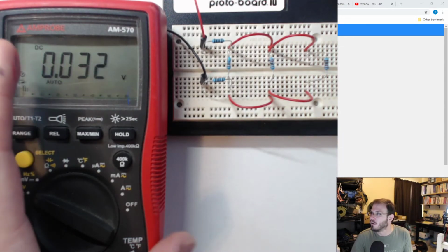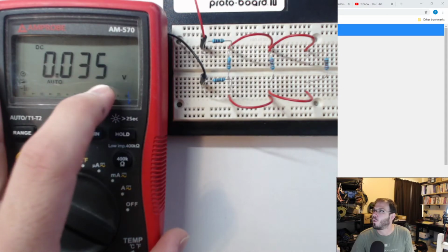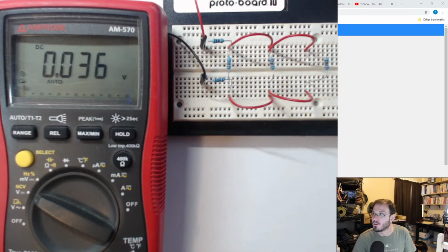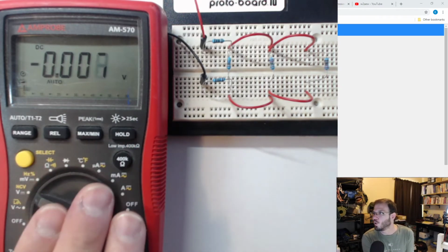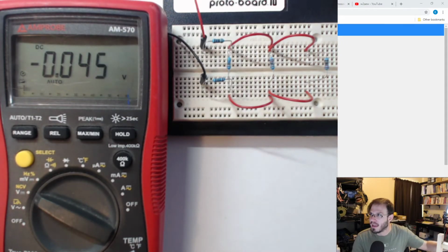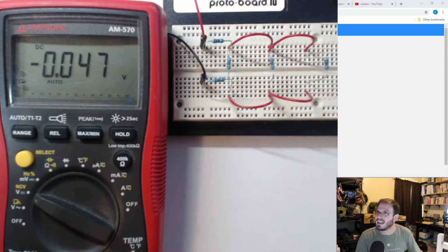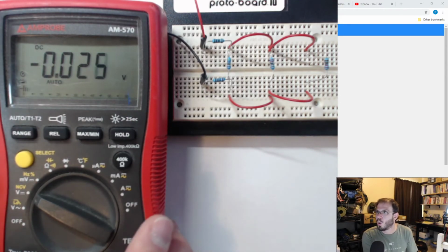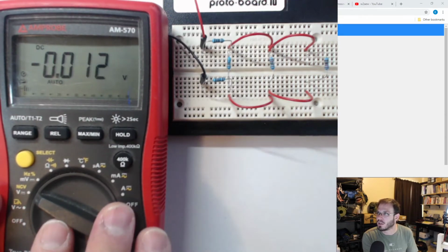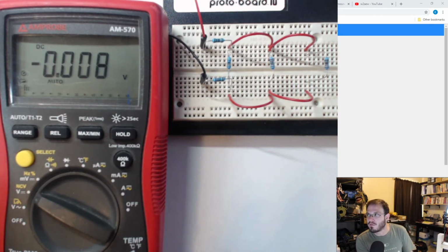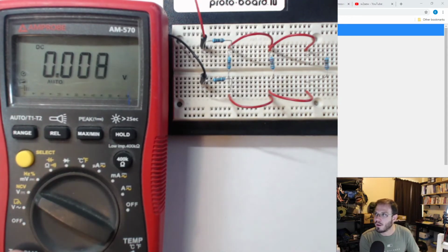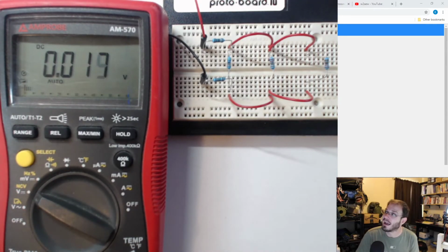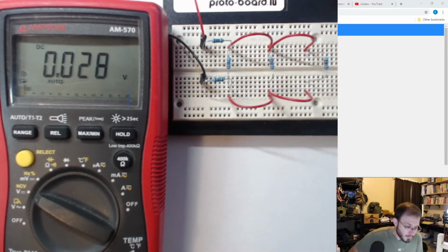Where I can't sacrifice is a multimeter if I want to get reasonable values to be measured. Okay, so that's why I say don't go for your super cheap multimeter, but you can get a super cheap benchtop power supply, because at the end of the day, this is the value that I'm going to adjust it to. So one reasonable quality multimeter is all you need. And quite frankly, for all other test equipment, you can go super cheap, and it's not going to make that big of a difference. Okay.